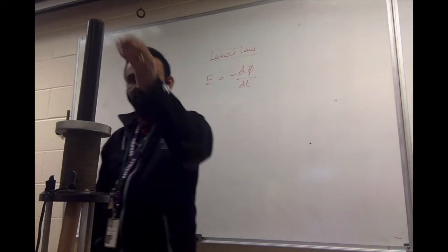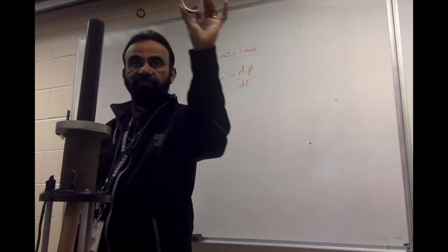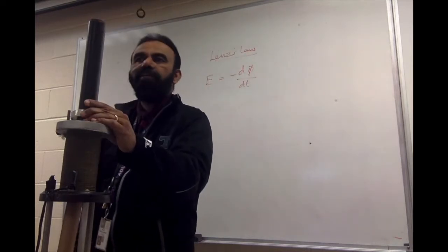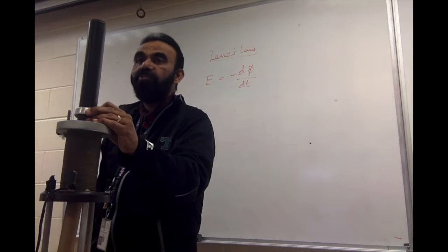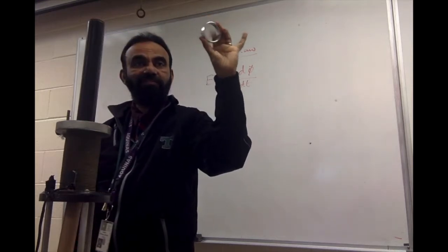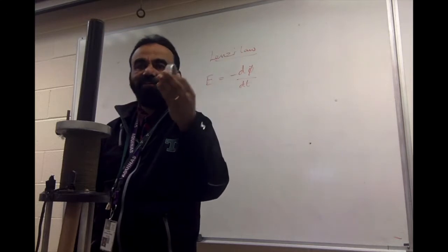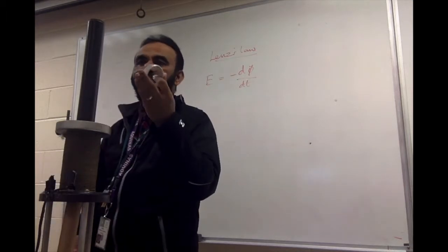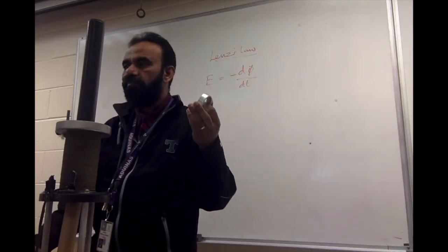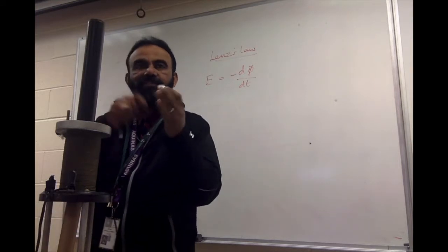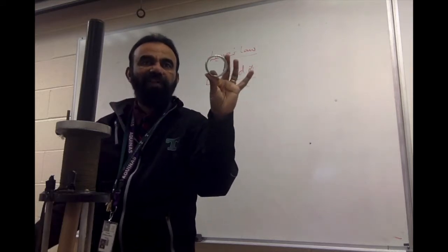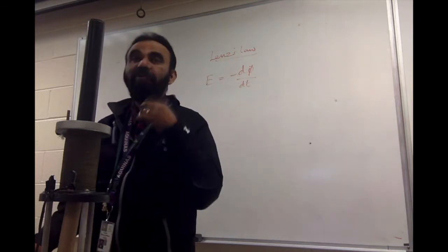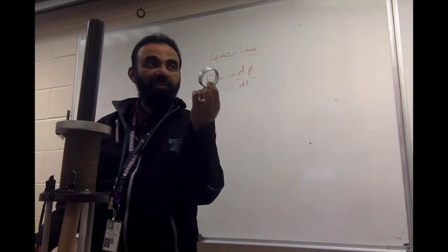Now what will happen if I just hold it here? Remember, there is a current flowing in this thing. If I hold it here forcefully, the current is going to be extremely strong. Why? Because this hardly has any resistance, right? So let's say the EMF generated inside here is just, say, 4 volts, and suppose the resistance of this is 0.1 ohms, which is actually far less than that. But if it is 0.1 ohms, what is the induced current? 40 amperes.